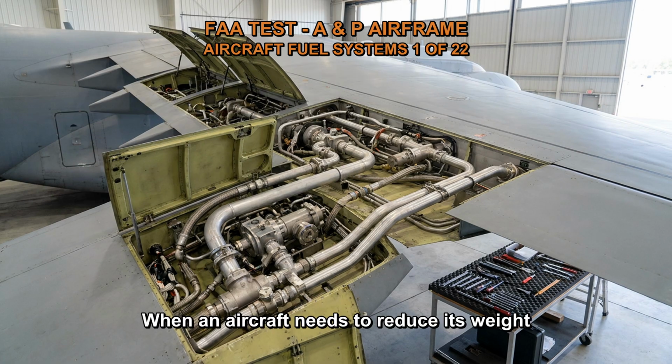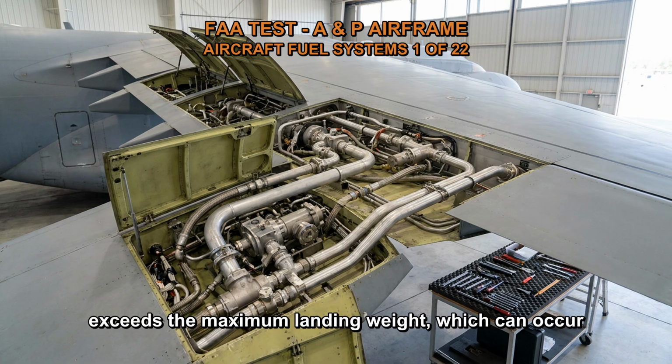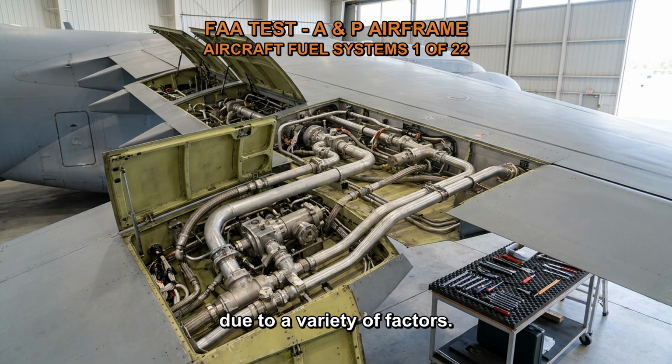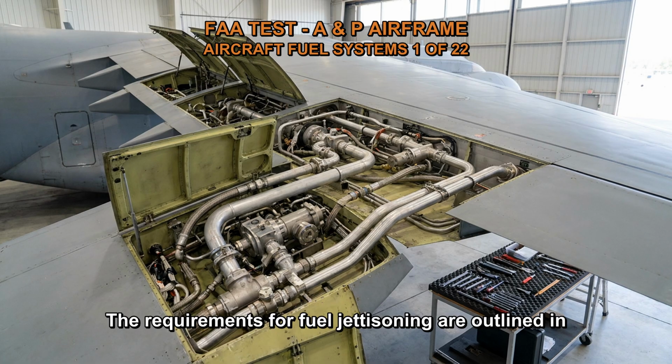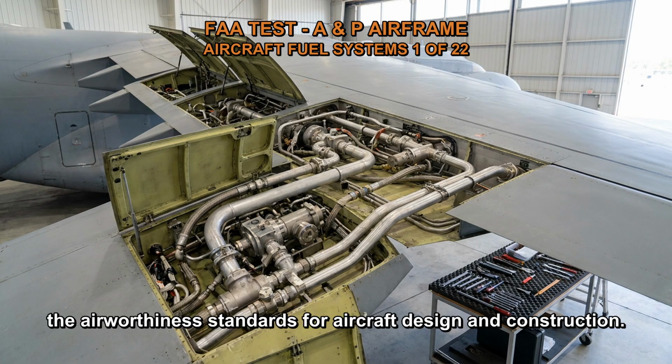When an aircraft needs to reduce its weight in order to land safely, it may use a fuel jettison system to rapidly expel fuel from its tanks. This is necessary if the maximum takeoff weight exceeds the maximum landing weight, which can occur due to a variety of factors. The requirements for fuel jettisoning are outlined in 14 CFR Parts 23 and 25, which cover the airworthiness standards for aircraft design and construction.